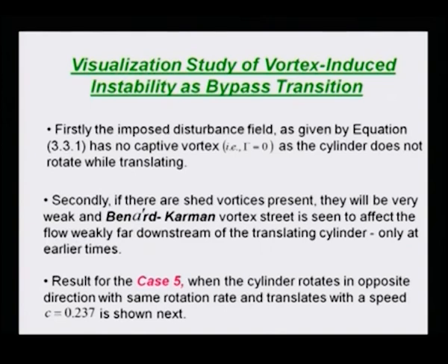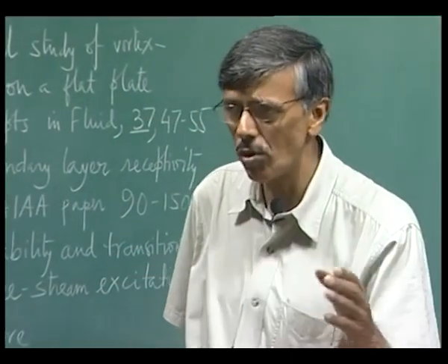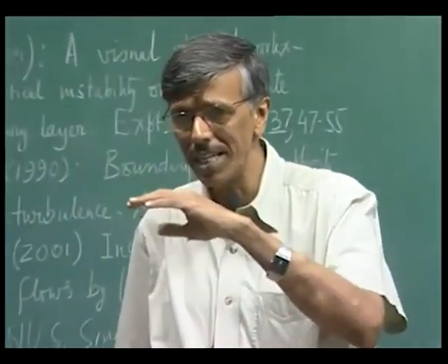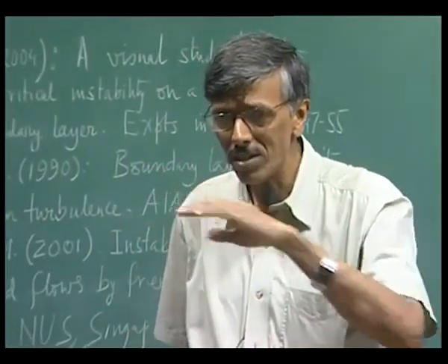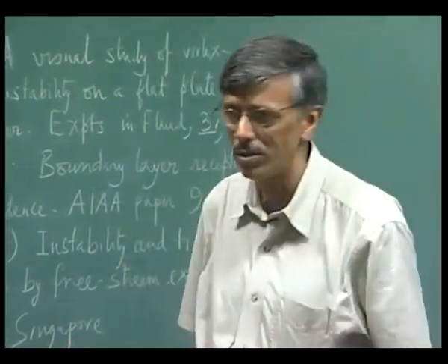Now, we show a case where the cylinder rotates in the opposite direction. The rotation rate is kept the same, and the translational speed is reduced. We have seen that if we make it dwell, make it go slower, then the adverse pressure gradient will be sustained over a longer time duration. So, if the flow is receptive, it will respond.